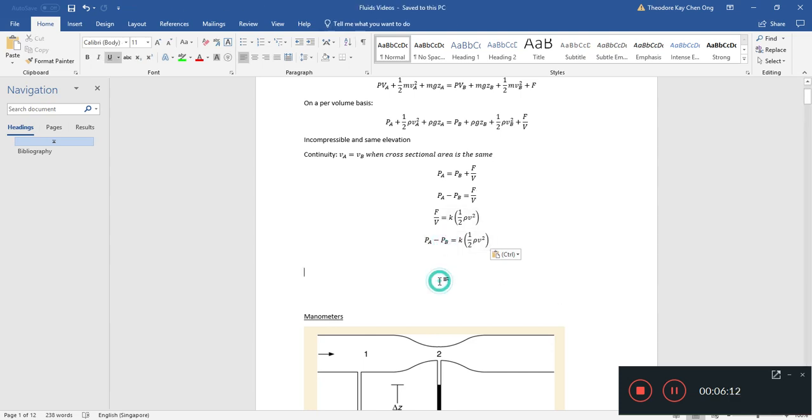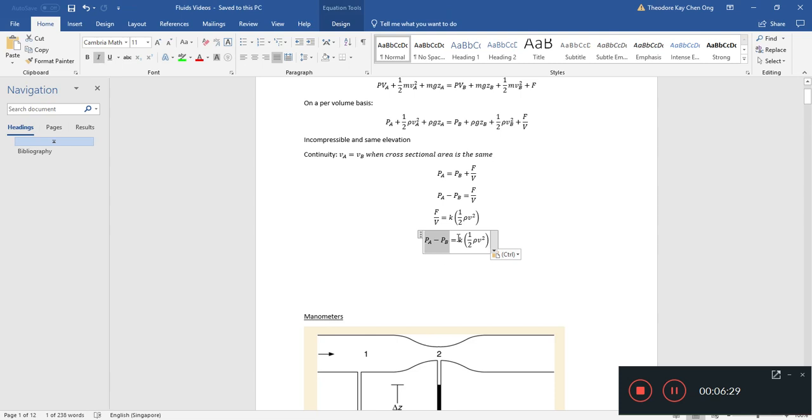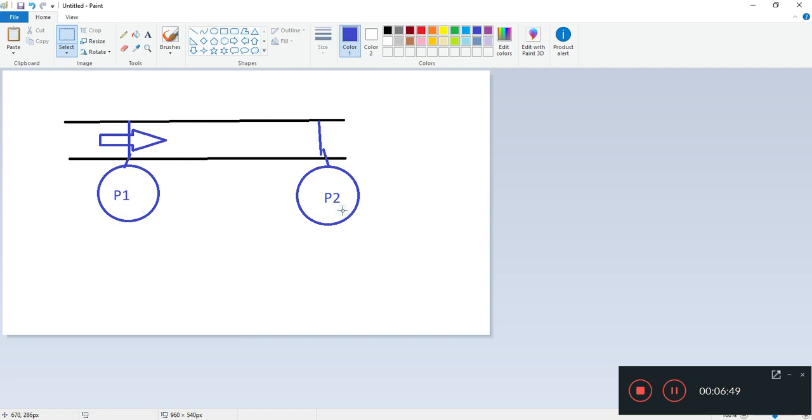Then what people will usually do is have some experiment in the pipe, have a flow, and then measure the pressure drop, P1 and P2. Then they'll substitute into here. There'll be a certain fluid velocity, and they'll have some kind of flow meter for that. That's why the Venturi flow meter is useful, or some other kind of flow meter. Then they'll take the pressure difference between this point and this point to find the pressure drop across.